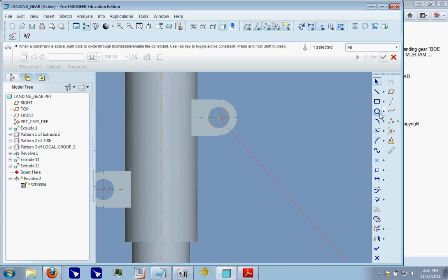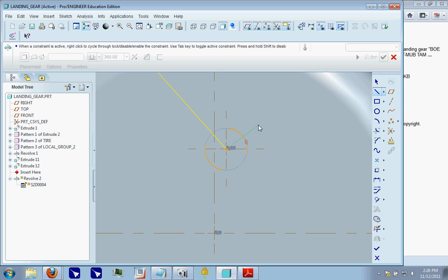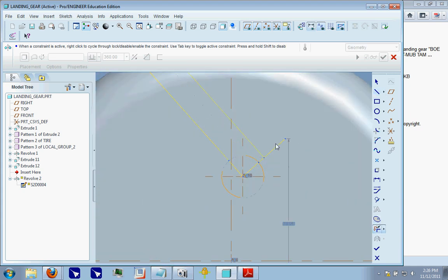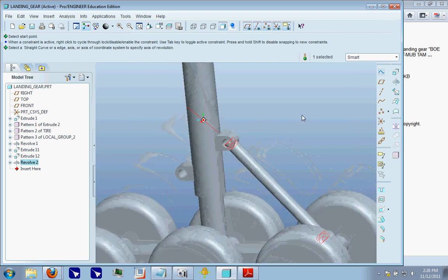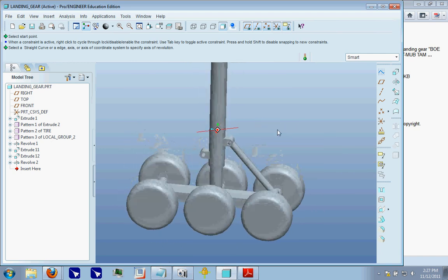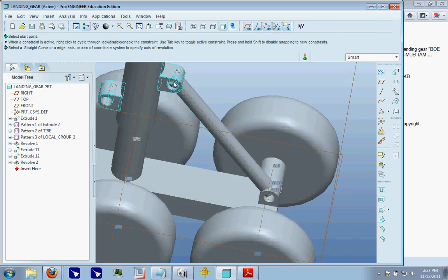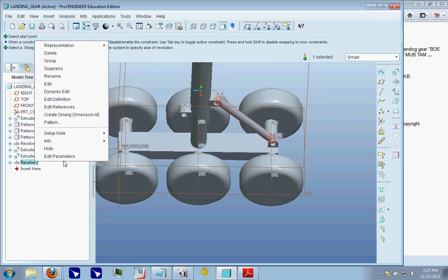So I'm going to come and just make a real simple cylinder coming out of there. There we go. And I'm going to make our center line axis like that and accept that. Now obviously I'm not really paying attention to this, but you might want to make it similar to this where you'd have a little jog in, little cut in like this, and you would also want to have another cylinder going through there, making a little nub on the outside. For this one I'll do it just a little example to show you, but for the rest of them you need to make them yourselves. I'm not going to do it just for the speed of this.